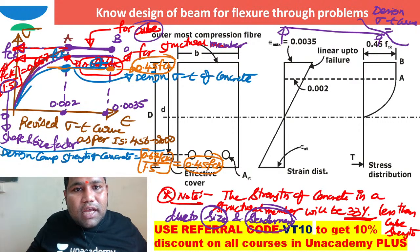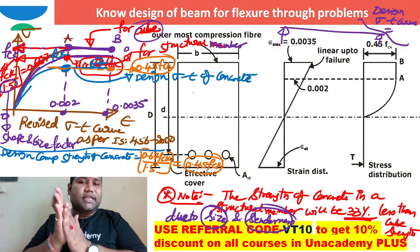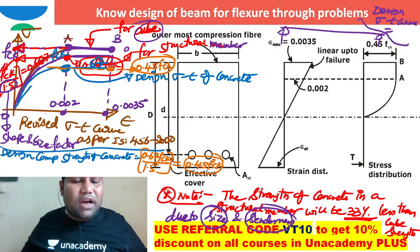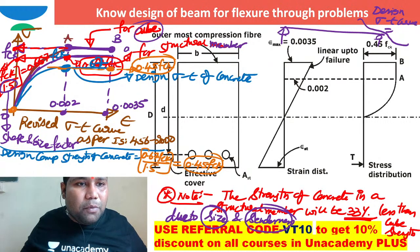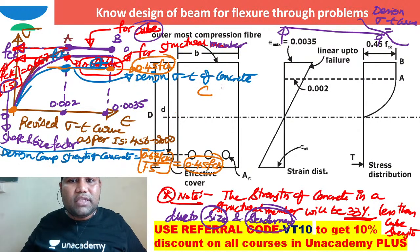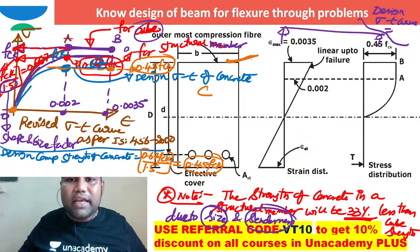So what is this curve called? This is the design stress strain curve. Now you can see this is the stress strain curve here. At this zero, what does it mean? At this point the strain is zero. This is the compression zone. In this compression zone, maximum strain is possible at the extreme compression layer. Minimum strain or zero strain is possible here.